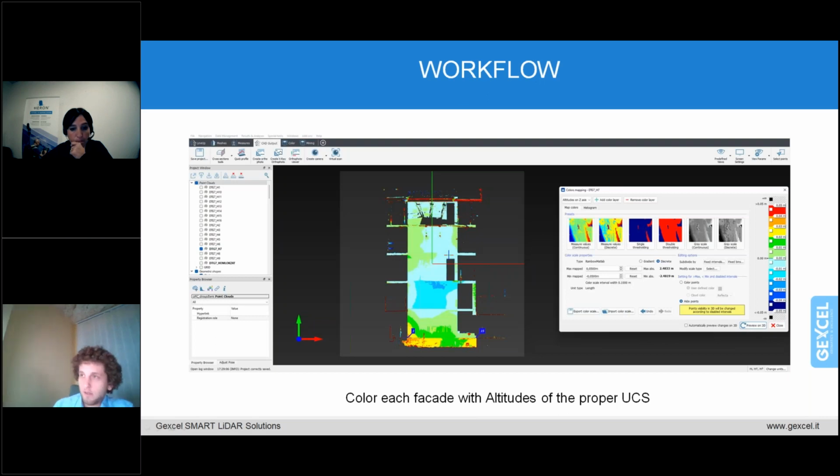And according to this coordinate system that we set up from the point pairs, we can also take over the case to the inspection tool and do the color deviation map. Again, we can choose the color ranging, the color distribution, however we like. We can even save the setup we do and reuse it again. I think I only have 3 different color scales for my whole life, and I just import the same setups again and again.